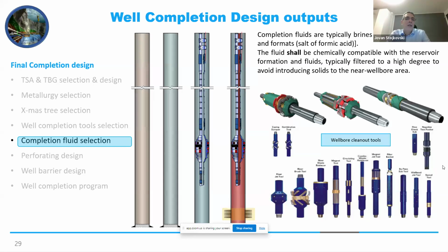But before we pump and exchange any kind of fluid with the completion fluid, we need to run a lot of wellbore clean out tools. We can do it in one run, putting a lot of magnets and brushes, as you can see here, to scrape all remaining fluids from the previous operations, like cementing jobs, and basically to prepare our internal well very clean.